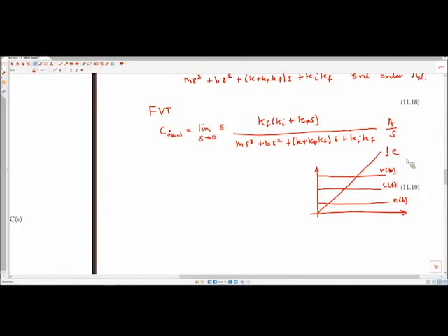And it's one of the more dangerous parts about integral control. You were explaining the situation where for some reason the actuator was turned off, right? You turn on the system and then nothing moved, and now this error term is integrating or winding up. So that could definitely happen. The most common case where you see this is, say for instance, I had my system and I wanted to spin 90 degrees, but there was some sort of feature on this and it ran into a wall, a mechanical stop that's stronger than the motors on the system, right?